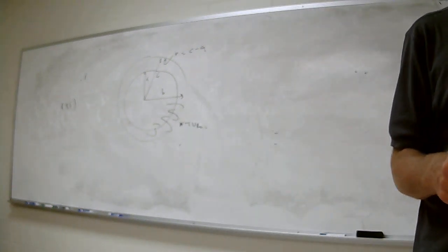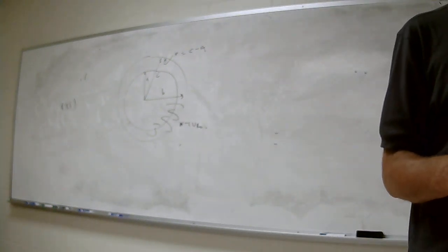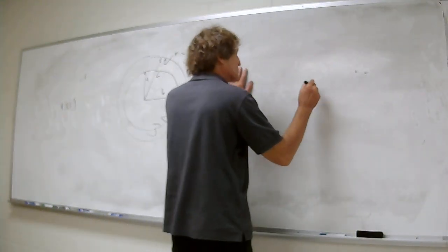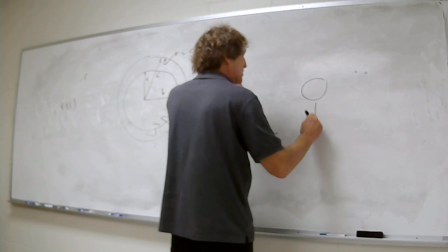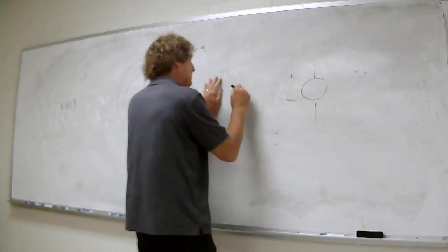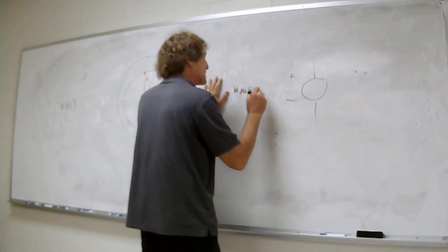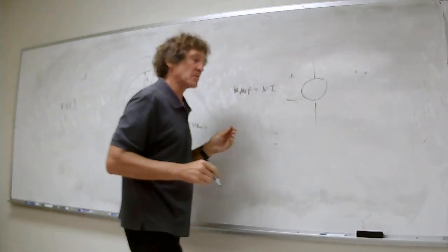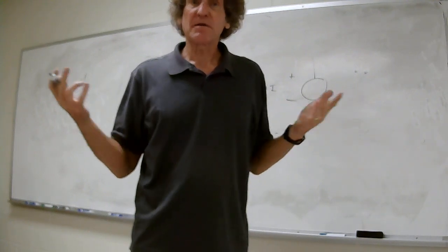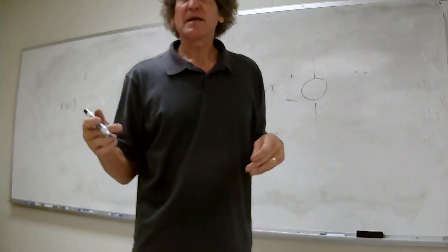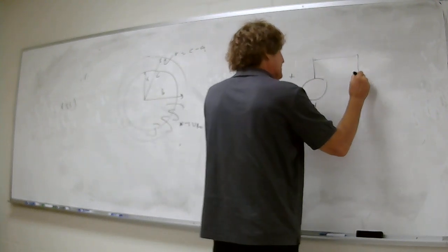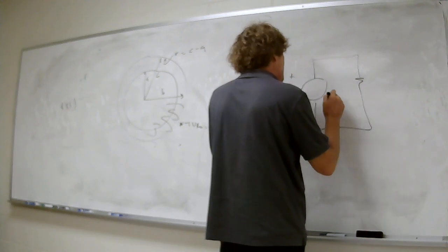Are you all with me on this, class? Now, please be attentive here. For an equivalent magnetic circuit, you start with the actual equivalent voltage, which is called a magnetomotive force. That MMF is going to be equal to simply the number of turns times the current in each turn. Do you all follow me on that? Think of it like a voltage. Now we're going to get the equivalent reluctance of this thing, and it's just like resistance. So if we want the equivalent reluctance,